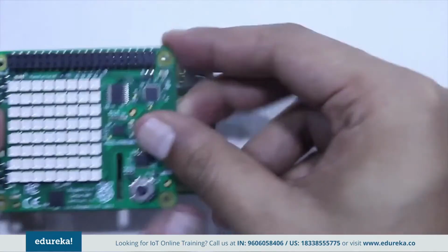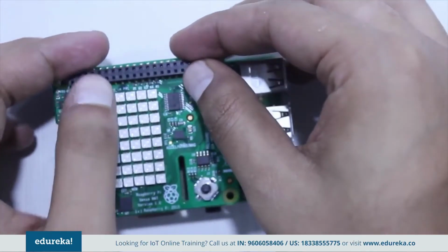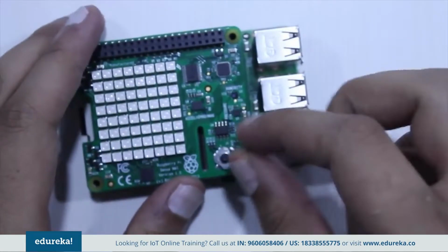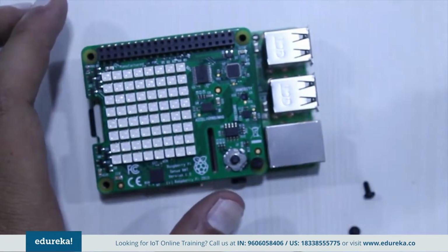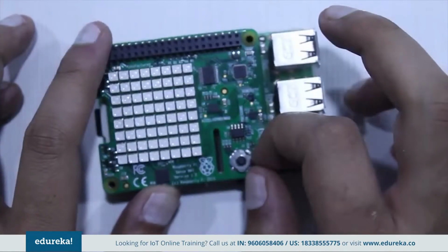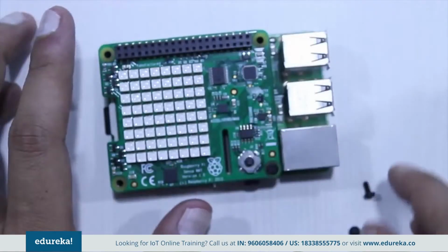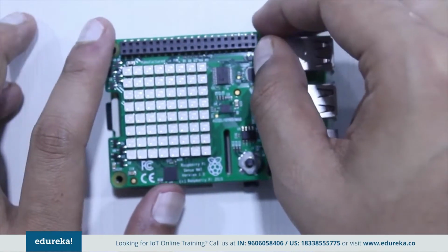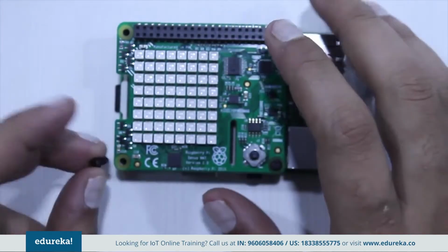It simply sits on top of the Raspberry Pi. Just make sure the alignment is correct, and once you're done with that, push it on top and the pins will merge accordingly. Once you do that, you can place the 4 screws across the different ends and tighten it up. Once you're done with this, you can use the Sense HAT for various purposes. We'll use it to measure the temperature, the pressure, as well as the humidity in this room. It has different sensors on it, and we'll be using them for today's demo. Let me put this up, and once it's all set up, let's go back to our demo.